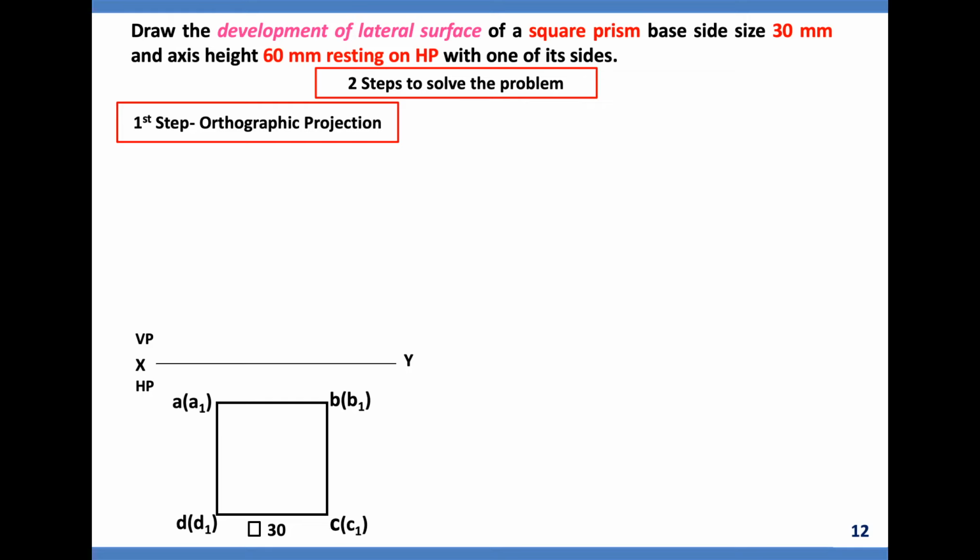Then you know the notations, or how to name it, which you have to refer for projection of solids. Since it has got top four corners A, B, C, D, bottom four corners A1, B1, C1, D1, which cannot be seen by the observer in the top view, hence they are represented in the brackets. Then do the vertical projectors, then draw diagonals.